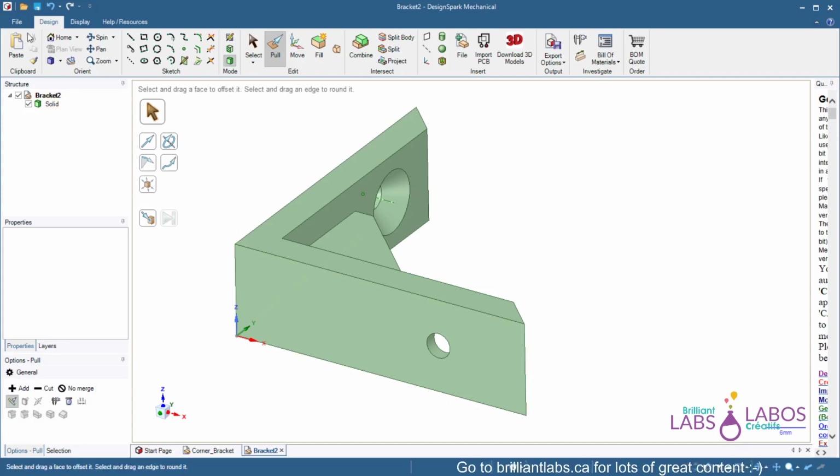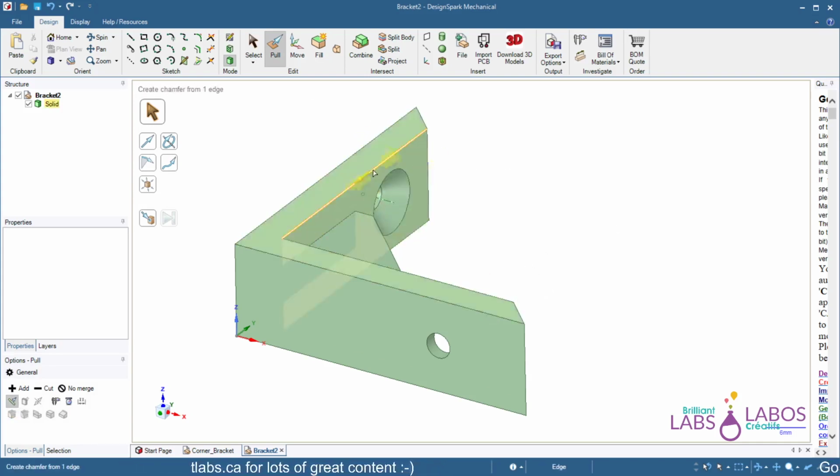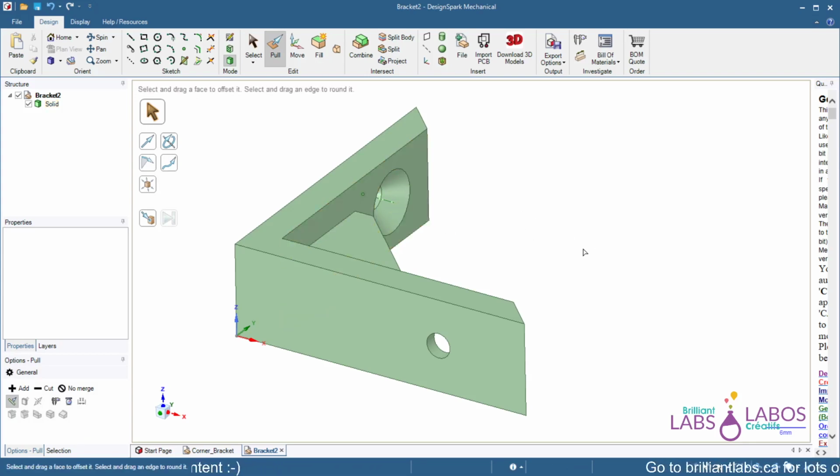This is why you might want to keep using Save As, because if I go Save As now, it will default back to STL, the last one I did. And the problem with that is if you made some nice changes to this, you won't be able to edit them because they will not be saved in the format that you can edit again.